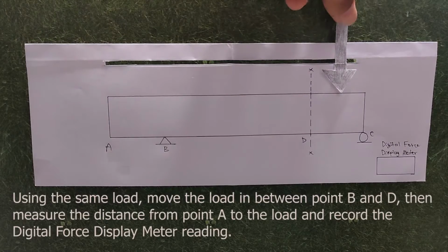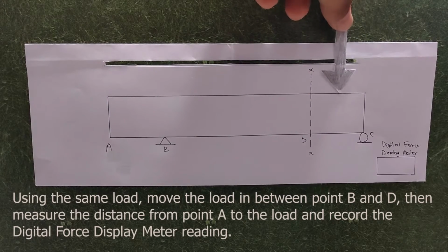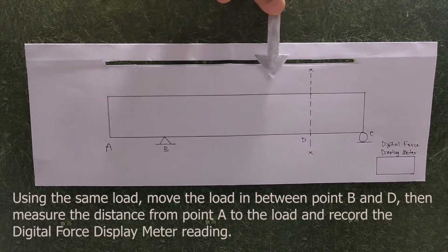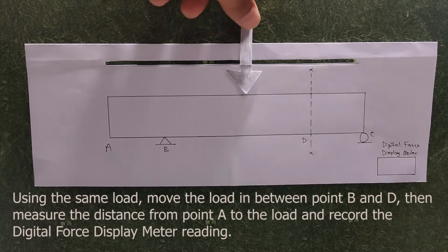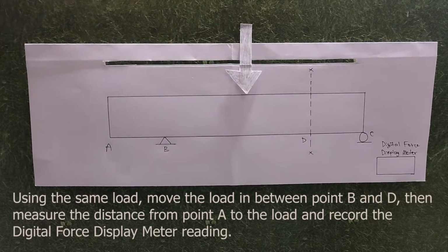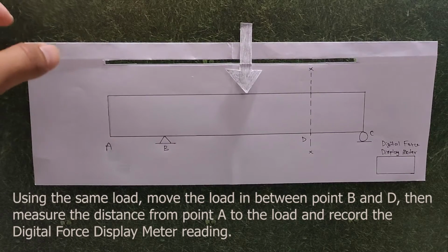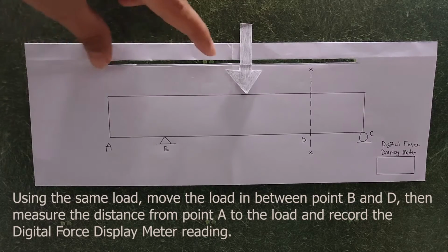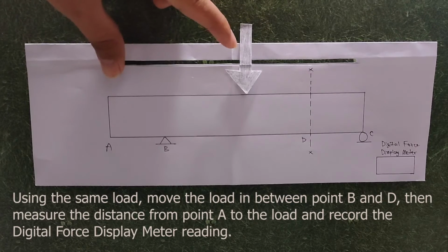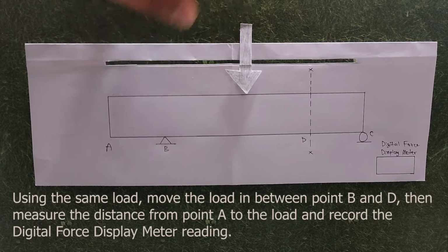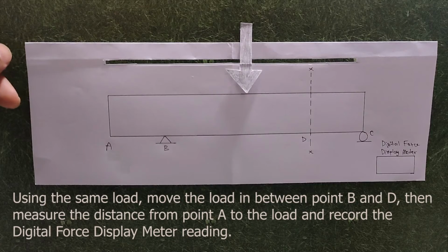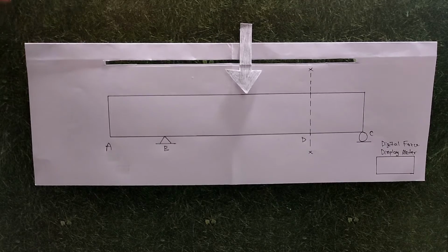Then we use the same load. We move it to the point between B and D, and we measure the distance from point A to the load and record the digital force display meter.